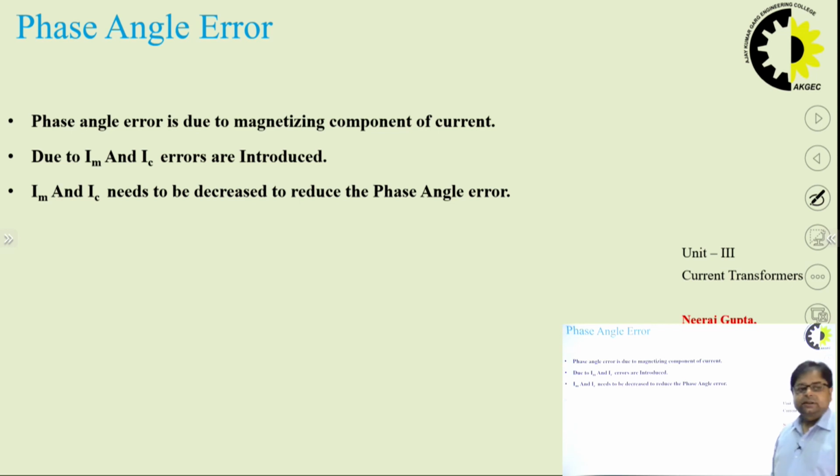Another important question we left to discuss is the non-opening of the secondaries. While operating, the secondary circuit of a CT should not be left open.